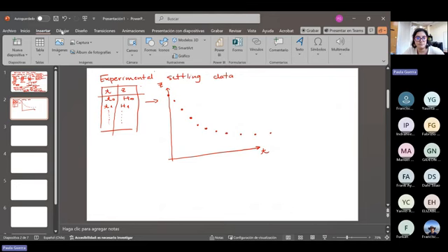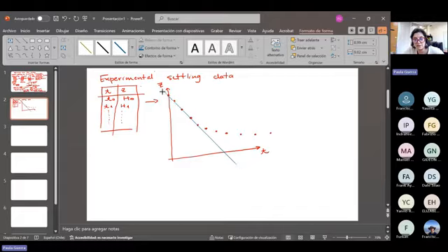Okay, so first I'm going to draw a straight line in the first settling zone where the particles are settling at their maximum speed. So first I'm going to draw a straight line that passes through this area over here. Then I'm going to draw a straight line where I can see that the concentration or the height is no longer changing.